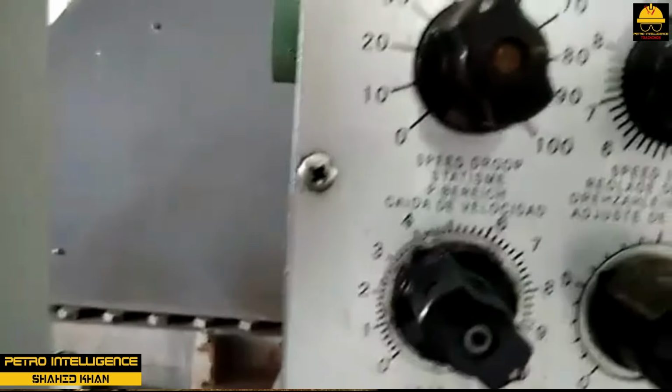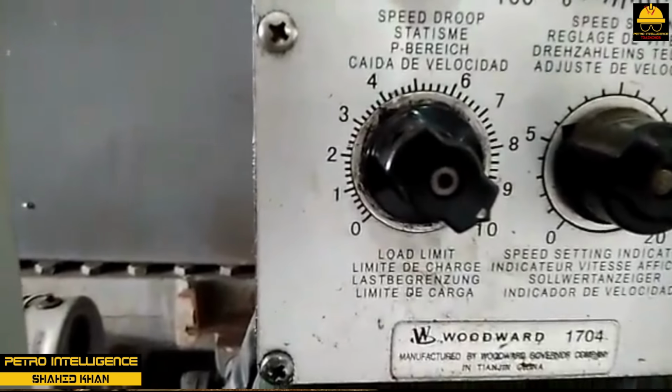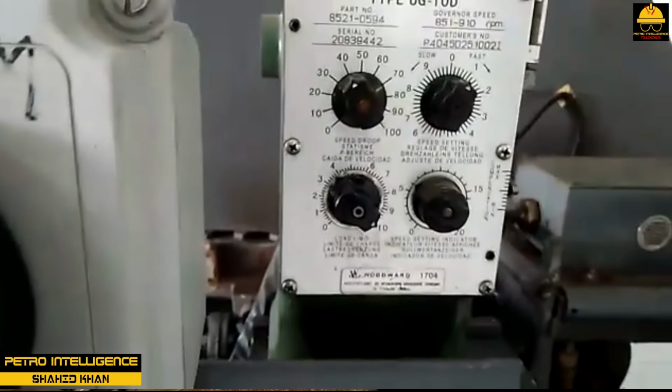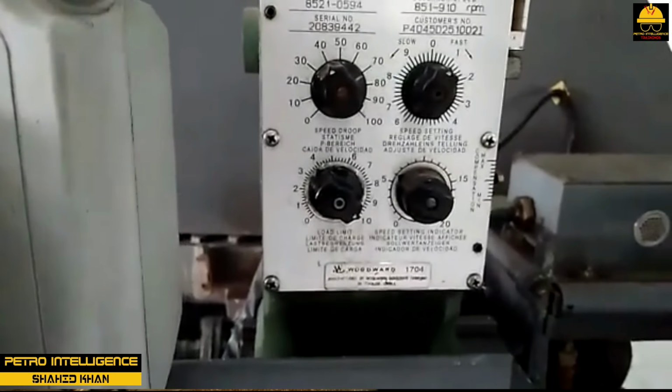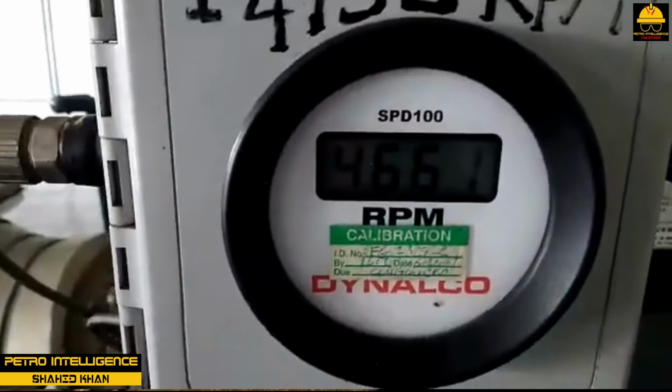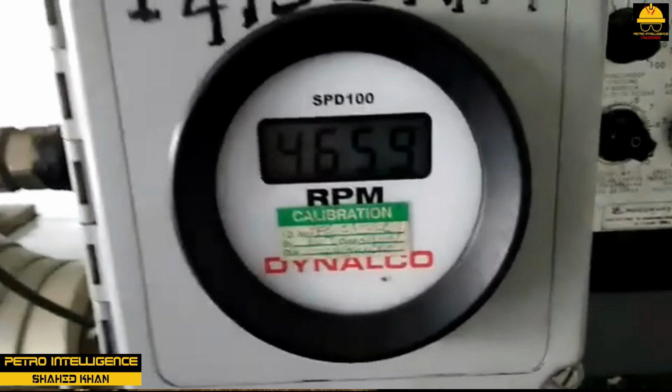Radial vibration increases when the turbine surges or after a cold start when the machinery passes through critical speed. Surging also can affect axial movement in the rotor. Higher bearing temperatures will accompany any of these problems. Operators should be aware that axial movement is the most important consideration when monitoring and troubleshooting vibration problems.